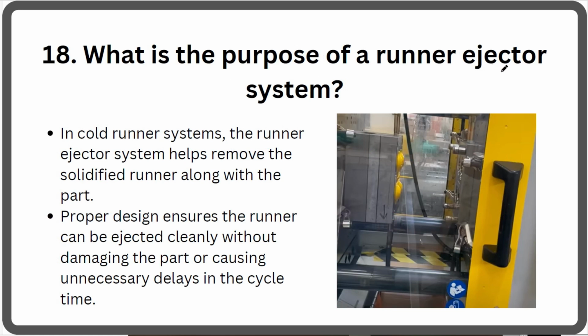What is the purpose of a runner ejector system? The ejector system is actually used to eject the part from the mold. There are different ejector pins, a number of ejector pins, and they will push the part so that we can eject it.